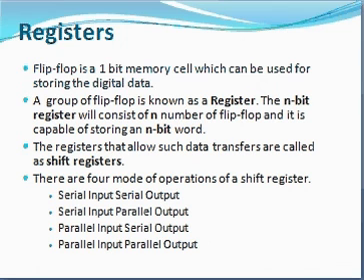An n-bit register consists of n flip-flops, and it is capable of storing an n-bit word. The registers that allow such data transfers are called shift registers. There are 4 modes of operation of a shift register: serial input serial output, known as SISO, SIPO, PISO, and PIPO.